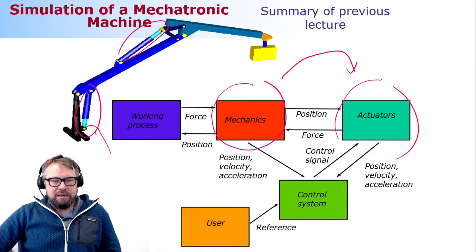The problem is that water hydraulics tend to be way more expensive than conventional hydraulics. The reason is that water is not a great lubricant, even though there is a phrase which says that water is the best lubricant. At least this is in the Finnish language, probably in English too. But in real life, water is not a great lubricant at all, particularly when compared to oil.